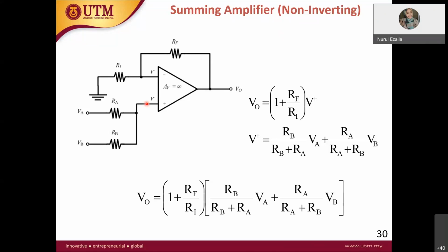The tip is you have to use the assumption V plus equal to V minus, and also I plus equal to 0, I minus equal to 0.